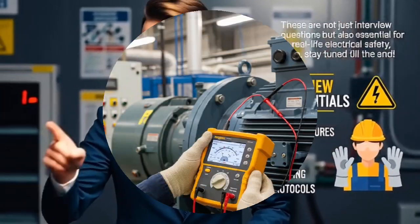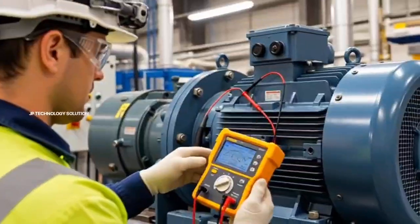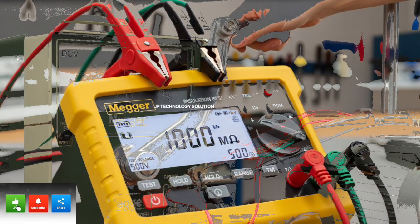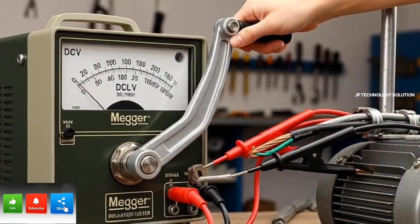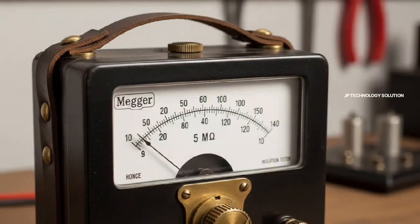Question 19. How is a Megger test done? A Megger is an insulation resistance tester. When we rotate its handle or use its internal battery, the Megger generates high DC voltage, usually 500 volts, 1000 volts, or sometimes up to 5 kilovolts for special tests. This voltage is applied between the cable or motor winding and the earth. The Megger then shows the insulation resistance value in Megger ohms.